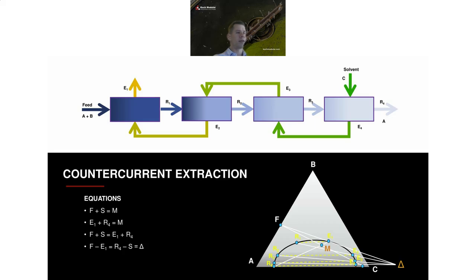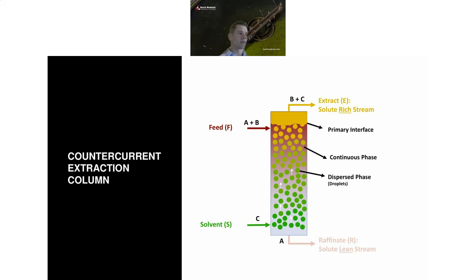So the process here is that you have your solvent flowing countercurrently against the feed. And by taking this type of approach, you can greatly reduce the amount of solvent that's required. And the more you reduce the amount of solvent, the overall economics of the process are going to be much more attractive, because almost always that solvent's going to be recovered downstream through distillation rather than extraction column. So you'll greatly reduce the energy requirements of the overall process and also the capital cost as well. And I'm going to be going through that when I talk about these case studies later in today's presentation.